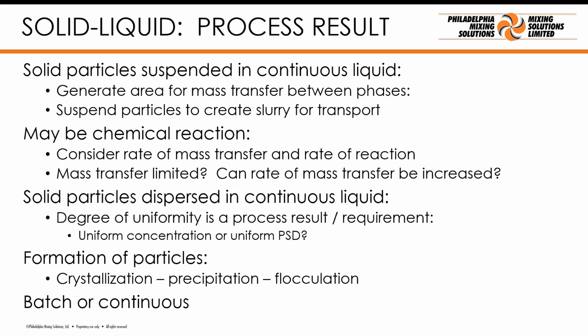I feel very strongly that we need more teaching about mixing. I'll give you, so if we say we scale up on constant Reynolds number, the power input per unit mass by the mixer will go down. I guess the point is you need to understand what about the mixing drives your process. What's the rate limiting step?